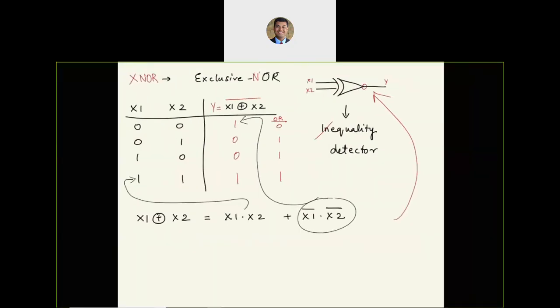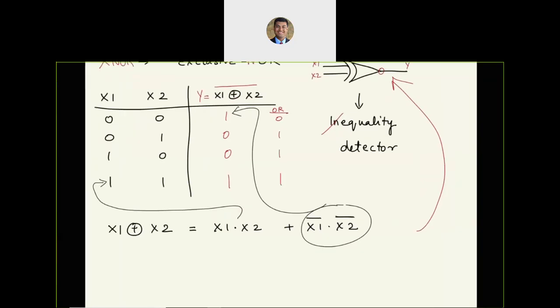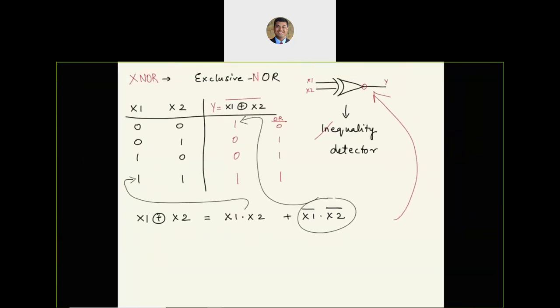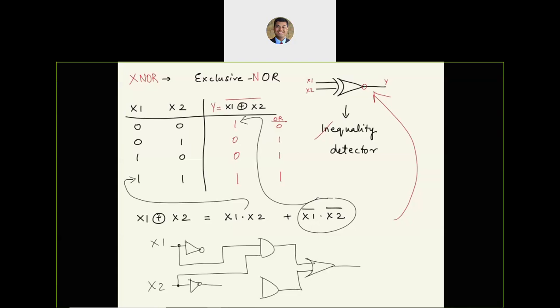And using the logic expression, you can probably sketch the logic diagram or the circuit diagram. So let's see, you're going to have 2 AND gates again. You're going to have 1 OR gate. These are going to feed here. We still need 2 NOT gates. We have x1, x2. x1 goes through, x2 goes through, x2 complement goes here, and this goes here.